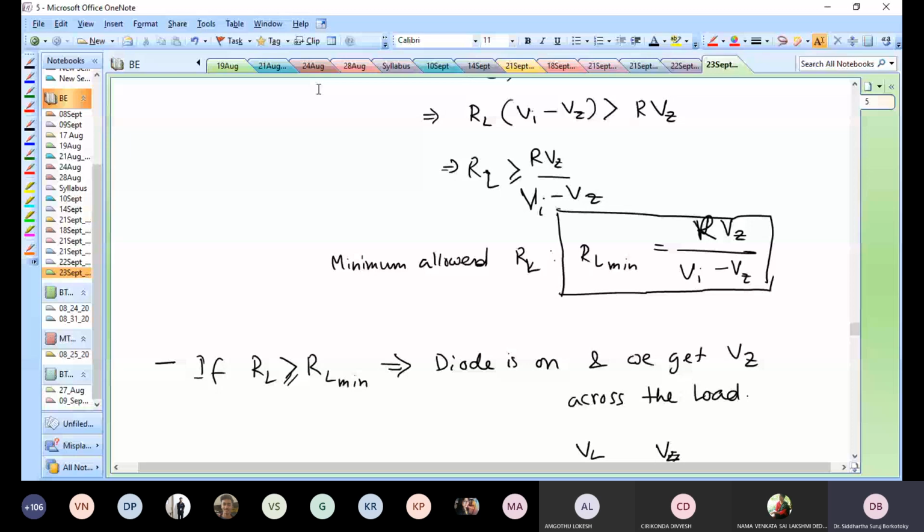So you already know that I am probably plugging this into some sort of an inverter, so I know what the output voltage of that inverter is. I'm going to plug it into some sort of a power supply where I know what the power supply is going to be, at least at an approximate level. So with all that, I can go ahead and say that please use a resistor which is a minimum resistance of this much. You can go above that, but do not come below that.